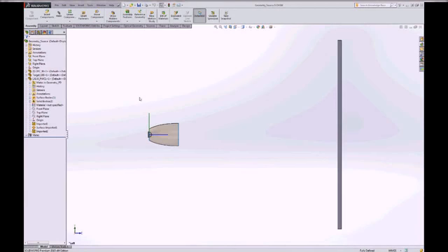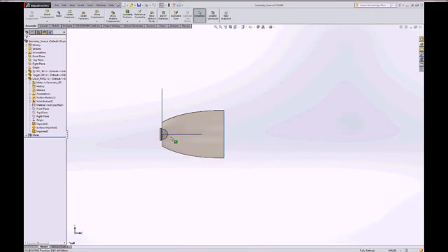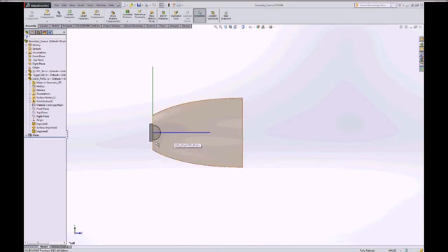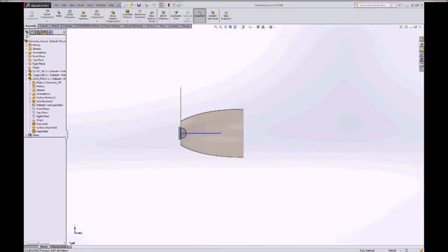Okay. All right, so we've defined our source. We've already defined our geometry. We've created a fully defined assembly using our geometric parts. So we verified our geometry simply by properly dimensioning them and fully defining them, if you will. We fully defined the position of the LED, but maybe we're interested in a little bit about what the energy distribution is. This is what we call the verification of the source.